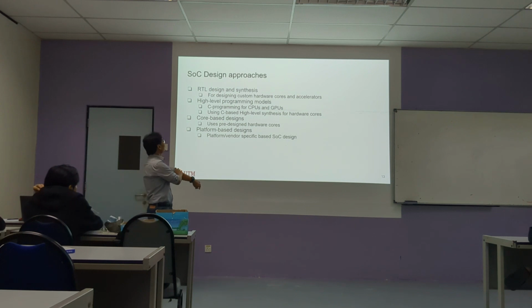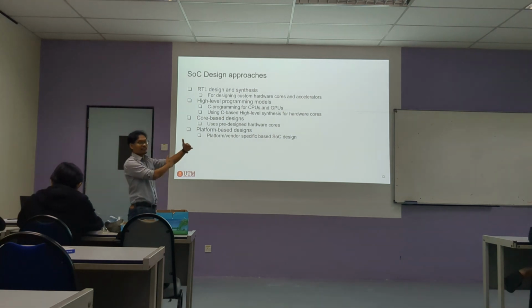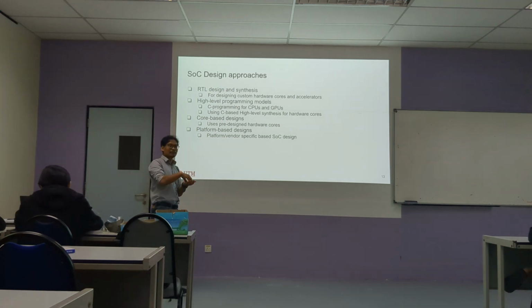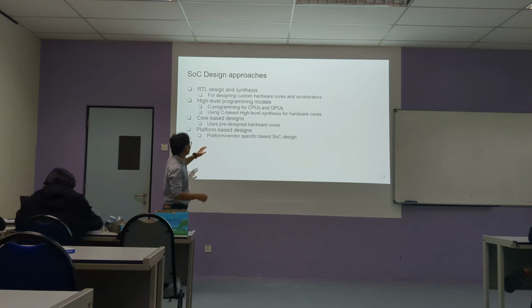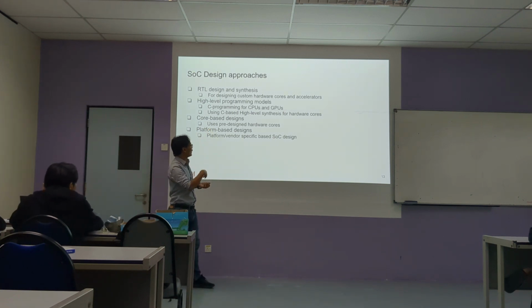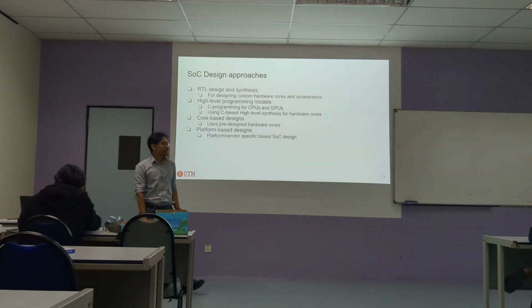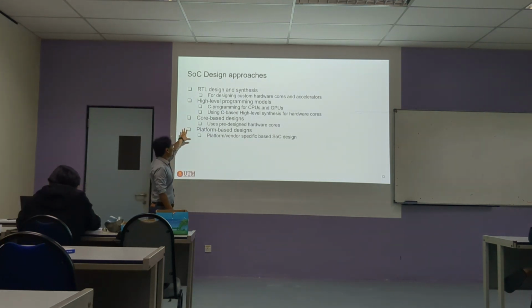Let's look at the SoC design approaches on the theoretical side. We start with the RTL design and synthesis. That's number one, the front end design: designing the hardware core and the accelerator. And then we have the high-level programming models to program the CPU and GPU. We can also use the C program to perform high-level synthesis and implement our hardware core. And then when we talk about designs, there are core-based and platform-based designs.